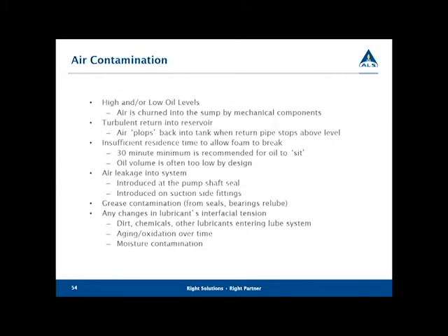You can have high or low oil levels. The air's churned in by the pump. Turbulent return on the reservoir. Insufficient residence time, which means the oil's not sitting long enough before it's pumped back in. Air leakage into the system. Grease can actually bring about foaming. A lot of folks don't realize that.